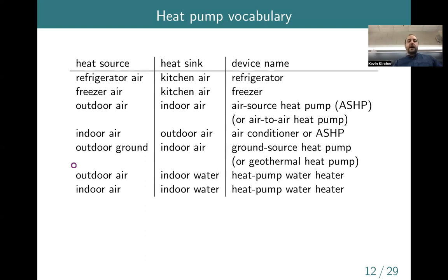Okay, so some more vocab here. If you're absorbing energy from the outdoor air and moving it to water inside, we generally call that a heat pump water heater, or an air to water heat pump as another term. And then if you're going from indoor air to indoor water, sometimes these things called heat pump water heaters will basically absorb energy, say from the air around them in the basement, which is itself conditioned potentially by another heat pump. And then they'll move that heat into the water.